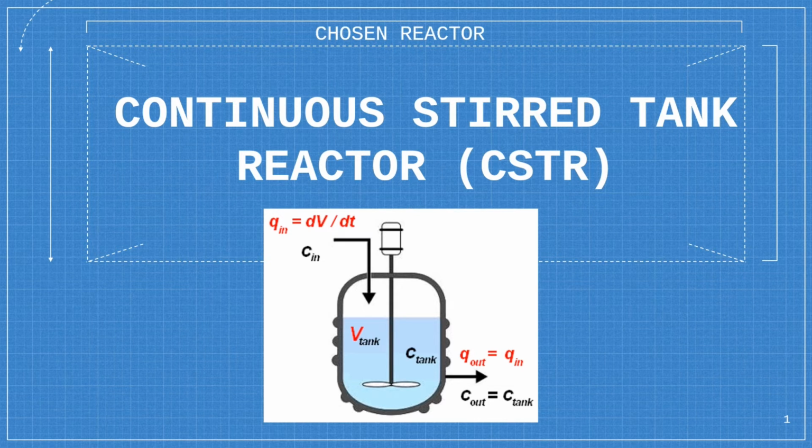This is because it is a steady-state system, which is a continuous flow reactor where the reactants such as untreated palm oil mill effluent are continuously fed into the reactor, while the products are continuously produced as well, and the condition of the CSTR doesn't change with time.